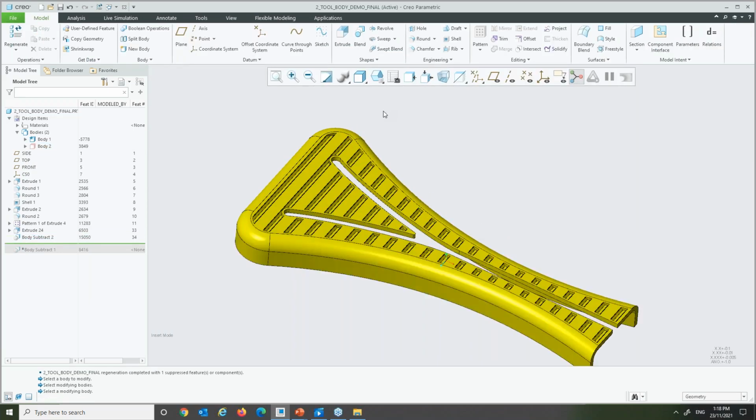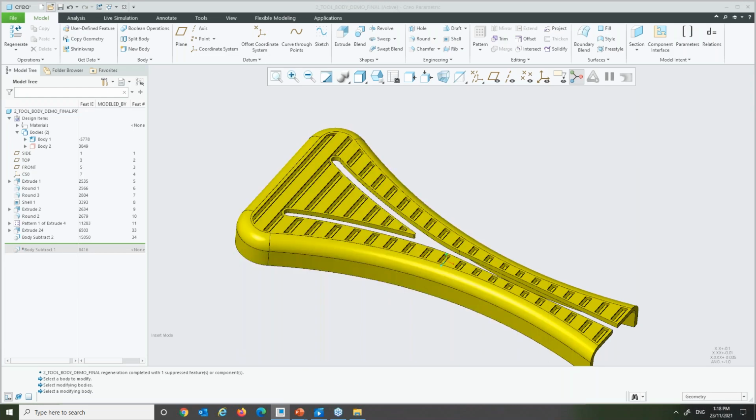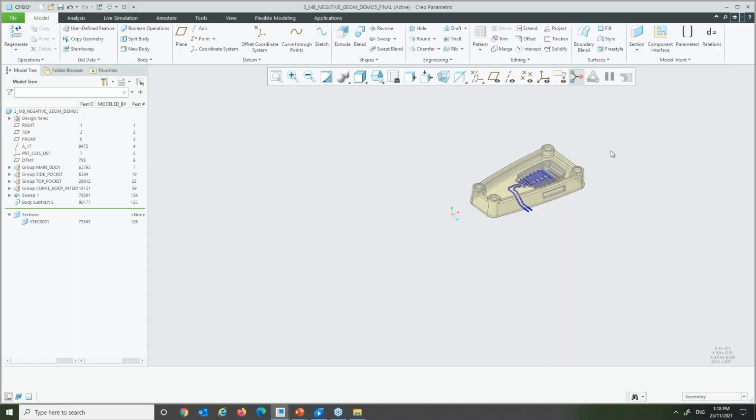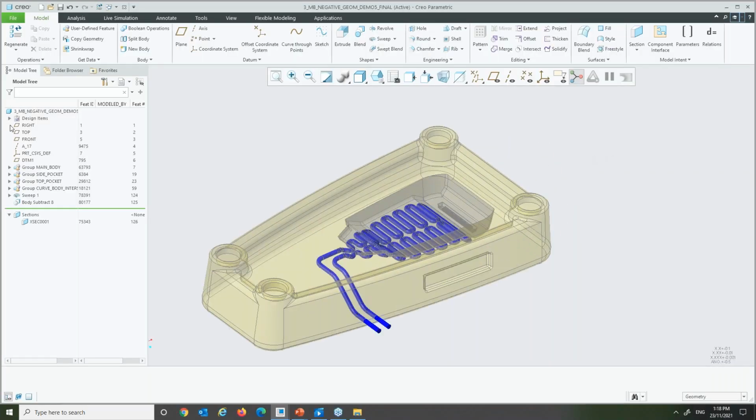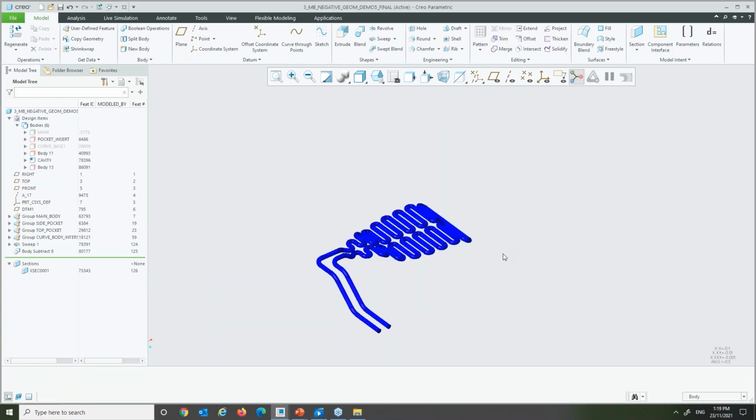It's very helpful in that case, and we can easily use solid modeling techniques inside Creo to do Boolean operations, which we were not able to do in the past. Of course, that is an additional benefit we get here. Very similar concept here as well. For example, if I have a few bodies here, there's a filter. You can easily select the bodies by changing the filter option here. And now if I hide that, this is the inside cavity which I would like to create.